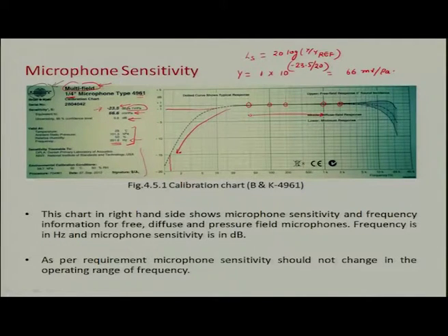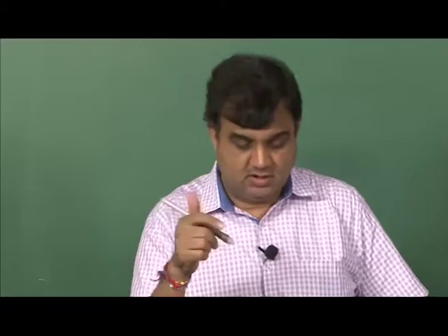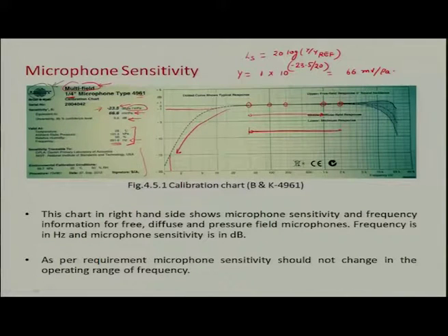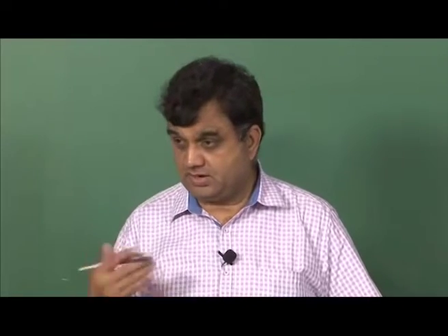So, this is the response of the microphone, and we had said that the response should be linear, which means the response should remain constant, and it should also be flat. What we see is that the microphone has a flat frequency spectrum in this range from 50 hertz to 2000 hertz. Beyond 2000 hertz it is no longer flat. So, then we have to see how it changes.